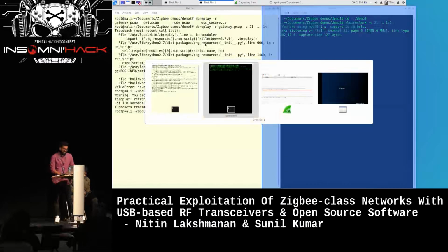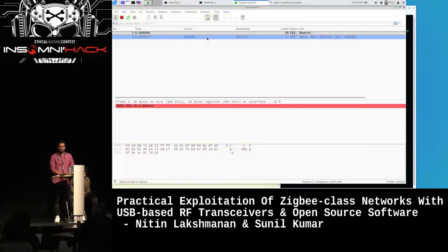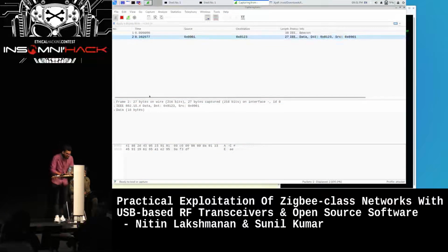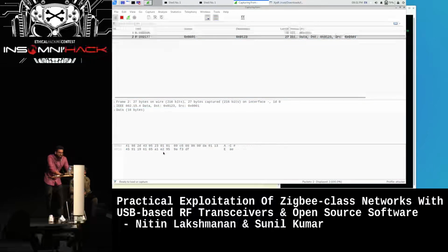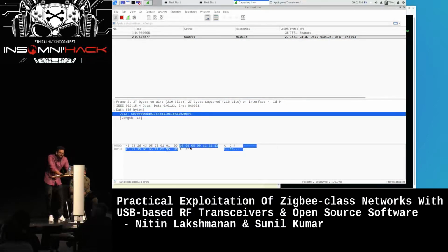As we have mentioned, there is something called HMAC in the packet. You can see that the payload has been bumped up by 16 bytes. After the DA011345, there is an 8-byte HMAC. We have truncated it because of computation issues.